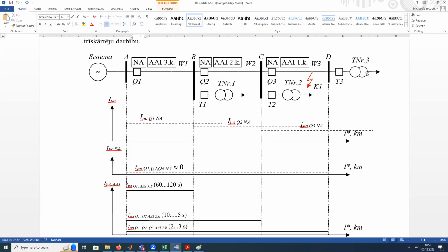But in a very cheap solution, there could be problems with these batteries, and we have a substation without batteries, and we have electromechanical relays that don't need a power supply. Cheapest solution. In this case, we have a limit for the reclosing. What if we have a fault, we disconnect the line, our substation is without power supply, and the only way the power breaker could operate is a mechanical power from a spring.